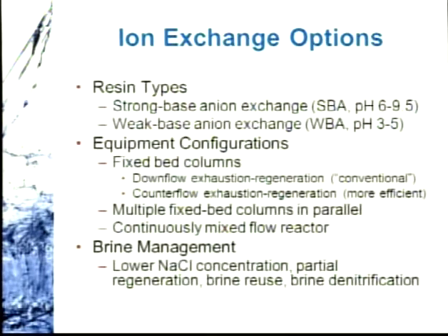There are some advantages to lower and higher concentrations, and to the approaches taken towards regeneration that can limit the overall brine waste, such as partial regeneration or the reuse of the brine after it's been used to continue to use it and decrease the total disposal volume. And then there are approaches that denitrify that brine and in some cases render it reusable for primary regeneration again later. And there are going to be some talks that will highlight that, I know, that will follow.